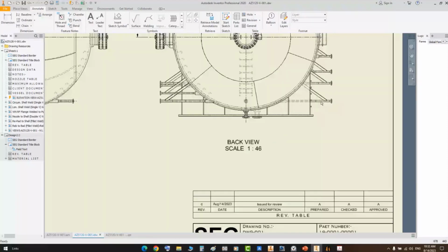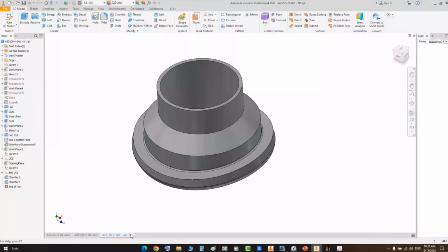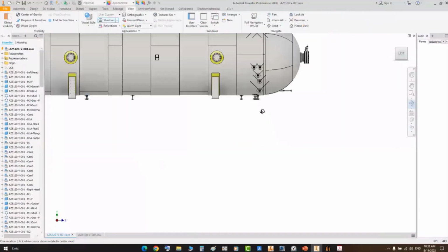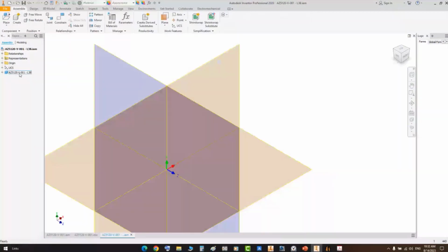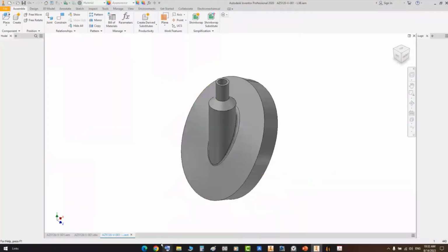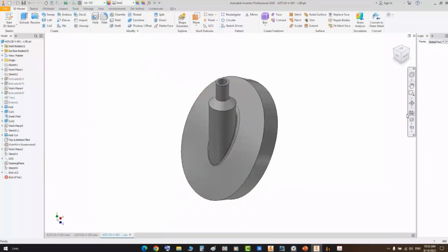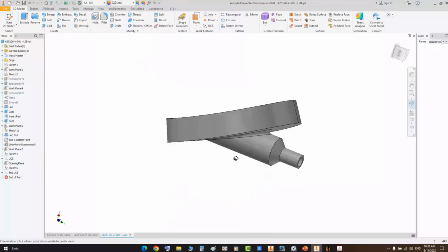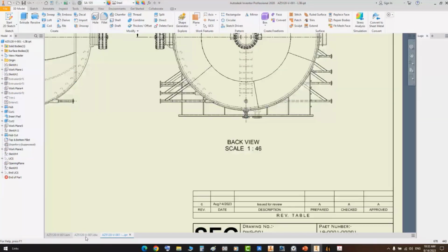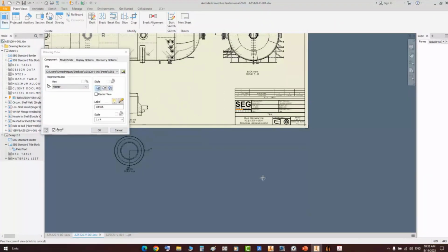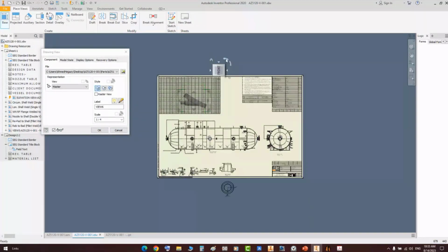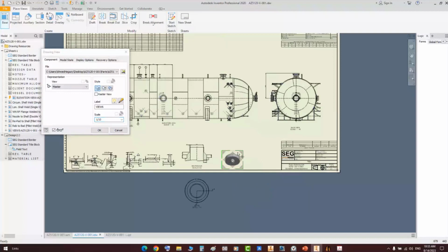Now let's check another nozzle, like the helicoidal nozzle on a shell. So let's select one of those forged hubs. Let's select this one, for example, and let's open this one. Here we have this forged hub, as you can see. Let's create a detailed drawing for it. So from here, let's add a base view for this forged hub, and let's modify the size. And this one, let's make it 1:10, for example. Like that, and let's move it here.